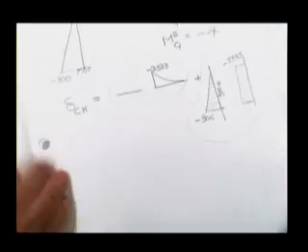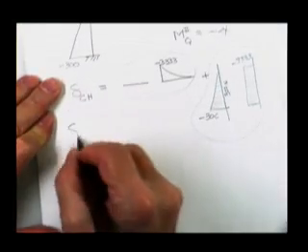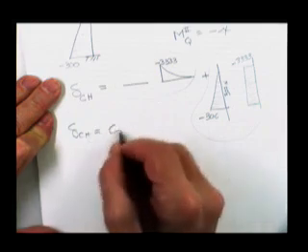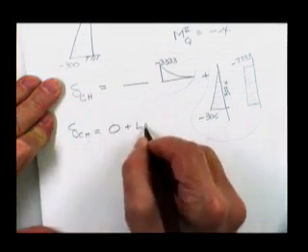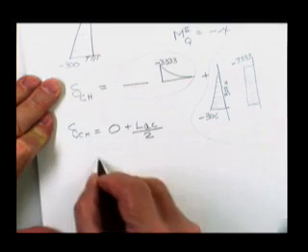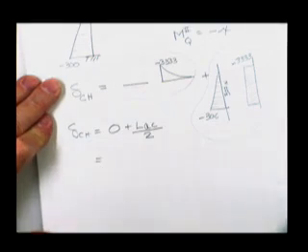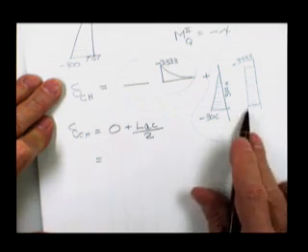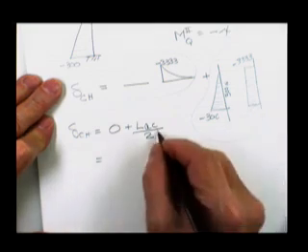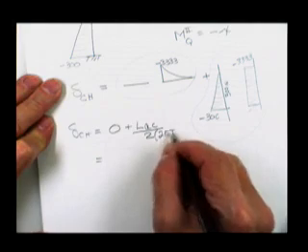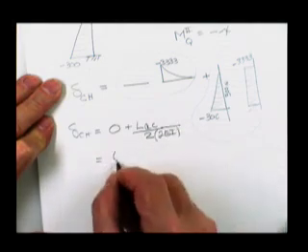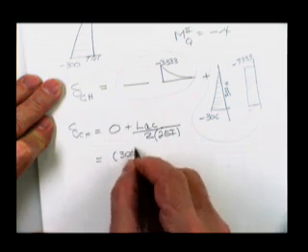And therefore delta at C horizontal is equal to 0 plus LAC over 2. And then, of course, it's divided by EI. And this is the member with the big EI, so we'll have to divide by 2EI. Now, the length is 300.